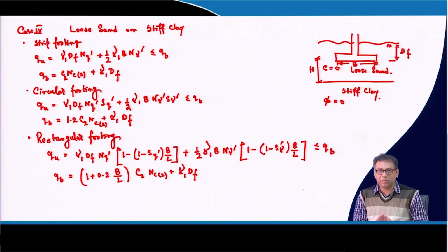But for these examples also, I have taken the full strength parameters. In the exam and the assignments also you will take the full strength parameter, but when you apply them in real design, I would suggest that you reduce it. But again, it is the engineer's choice, the engineer's judgment, whether he or she will take the full strength parameter or the reduced strength parameter. But these are the facts that I have discussed.